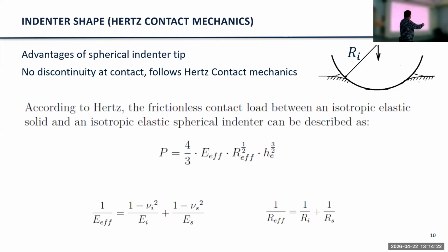And we can also define, I'll show you later, the entire stress field underneath the indenter. Now, this is the case where, because magnesium is nearly elastically isotropic, these analytical equations that Hertz derived maybe 150 years ago can be directly applied.